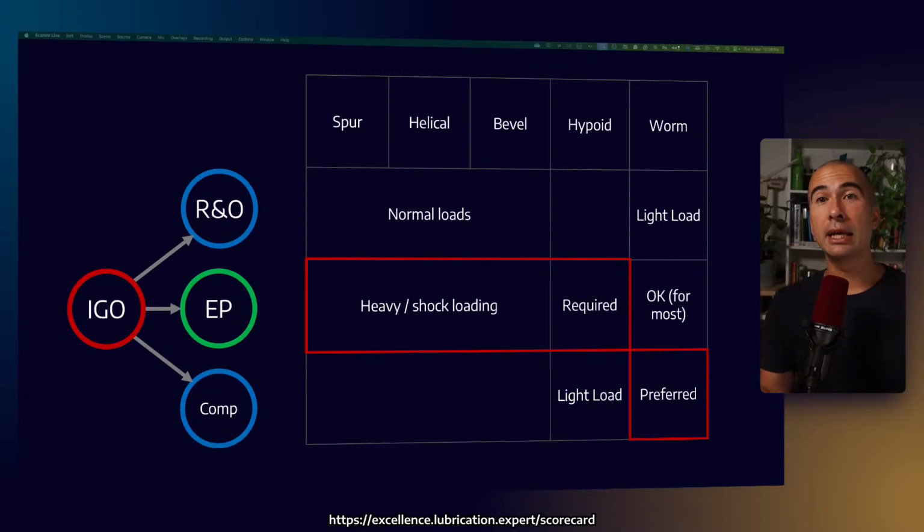Oh, okay, good question. Sometimes what we will see is oils used in different circumstances. A classic example of this is the tractor hydraulic fluids. If anyone has worked around farm equipment, there are tractor hydraulic fluids for, let's say, Massey Ferguson or Case New Holland, where we have a product that is a unified system for the hydraulics, as well as the gears, as well as the transmission. So in that case, we are over-engineering the lubricant so that it can do all of those things at once.